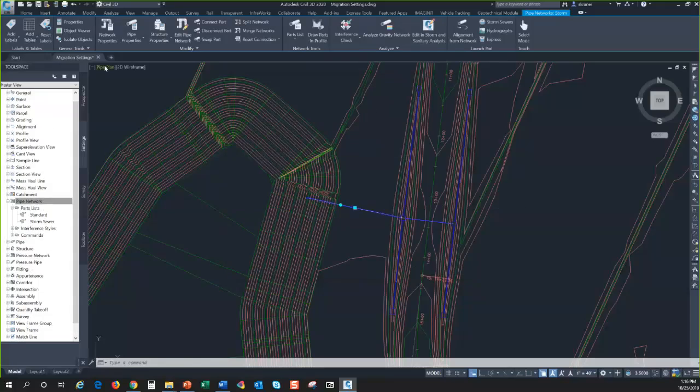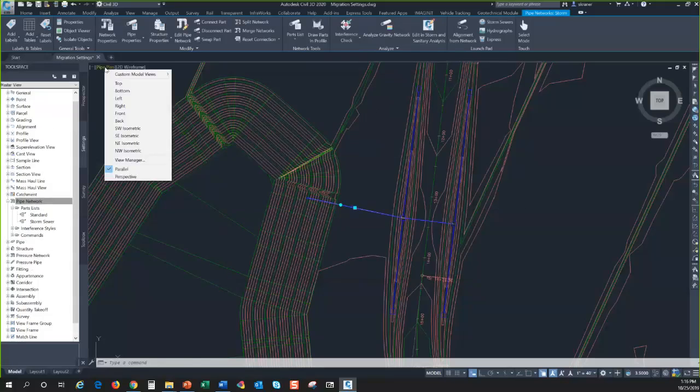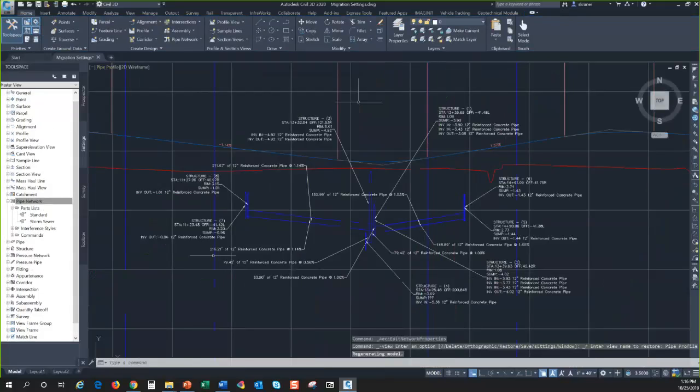I'm just going to go over and show you the same system in profile. So here we are. This is set up on the roadway profile. And so some of the elements are stacked here. I tried to separate the labeling so you can see what's here. The biggest thing to point out here is I've laid everything in according to basic rules. Everything's sloping from these outer drop inlets into the center inlets here in the middle, and then running down and finally down to this head wall.